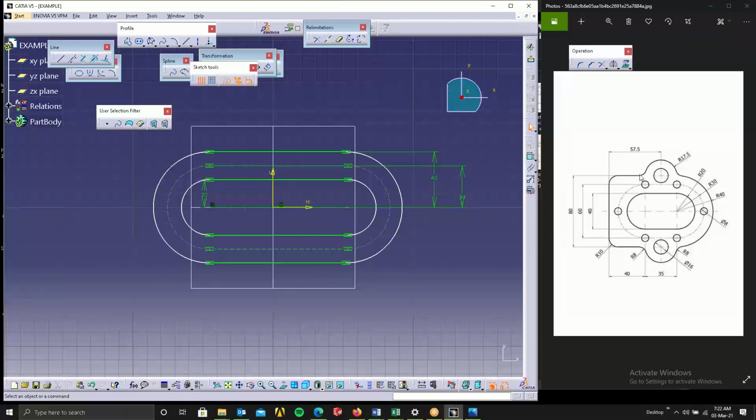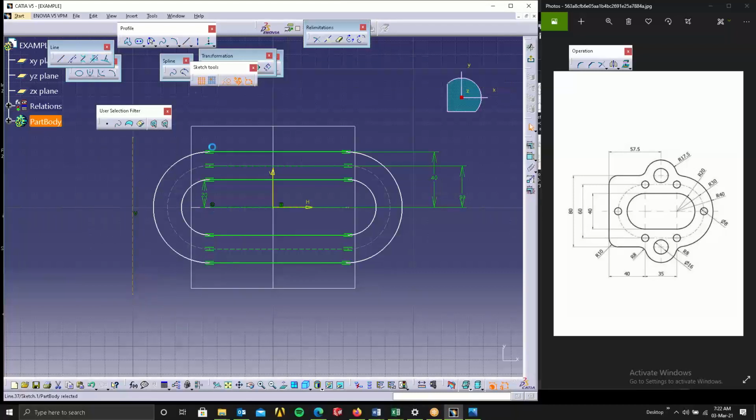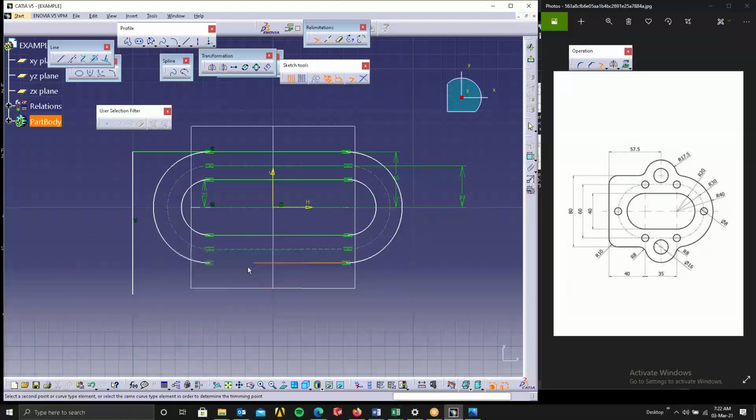So next, this thing has a rectangular back. So what I can do is draw a straight line and make it a normal line. Next is this distance from here to here. So first this is done. Take the extend command. Select this side. Take the extend command again and select this side. That is done. Then you can just trim this circle off. You don't want that.